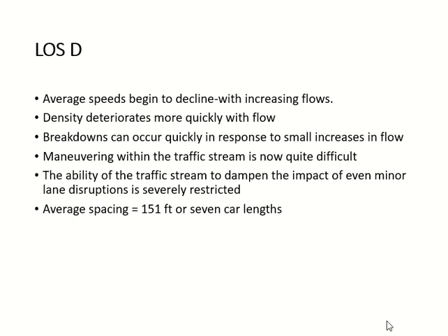Then level of service D is where you will definitely see a decline in the speed. Okay, so even if you are going in your own lane, you don't have enough spacing to choose your own speed. So you have to be more vigilant, and you have to now decrease your speed. When the speed decreases and the spacing is decreasing, that means the density is now increasing rapidly. In this case, you are now very close to the breakdown condition. This is not breakdown, but now you are getting very close to the breakdown condition.